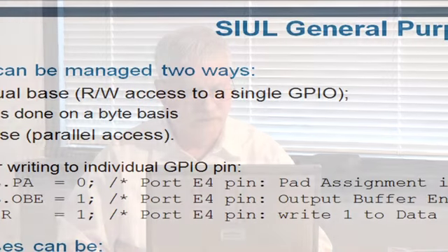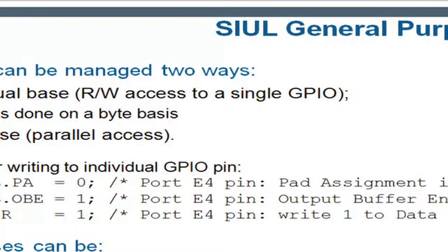in the register window. Now for ports, we can have access for read of 32, 16, or 8 bits, and for writing as 32, 16, or 8 bits if they're not masked. We have a mask capability to support accesses, so we can write to certain pins, give it a value, but just mask out certain ones, so some pins are affected and some aren't.